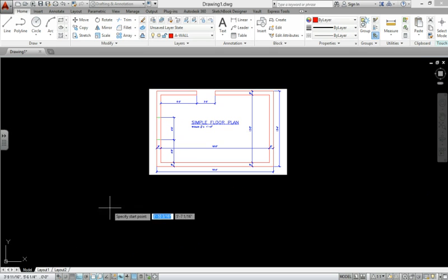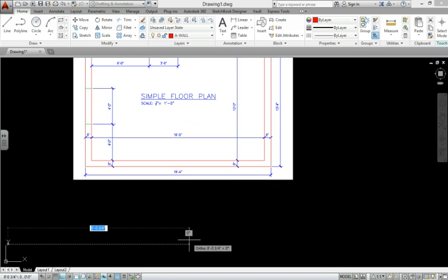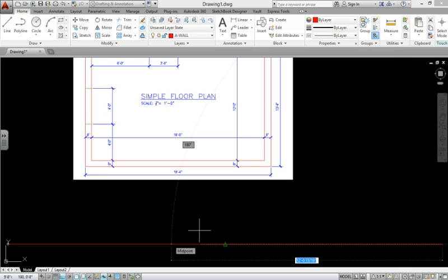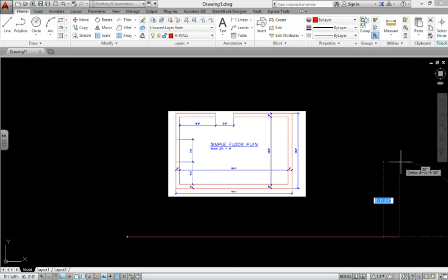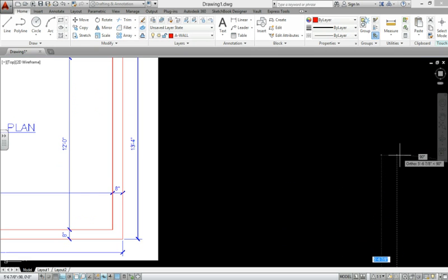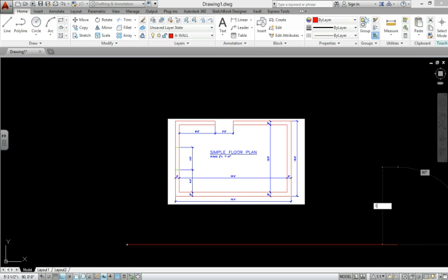So we're going to go to the right. I click here, point to the right, and I need to type in 19 foot 4 inches. So with your mouse, you would type in 19 foot mark dash 4 inches. You also could just get rid of the dash and just type in that. Enter. You can see it's really large, so we'll zoom out, we'll point up, and I can type in 13 feet 4 inches. 13 feet 4, shift, same button on the keyboard, inches.